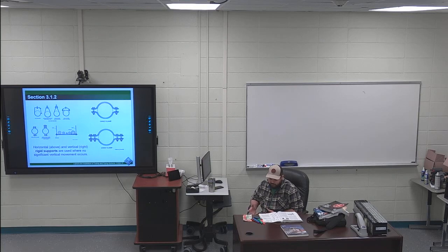Just protects your stuff from growth. This last paragraph on page 33, first two sentences are highlighted. A snubber resembles a rigid restraint. However, it contains a mechanism that permits movement in the presence of slowly applied loads but locks during rapidly applied loads. I think they have a hydraulic snubber.